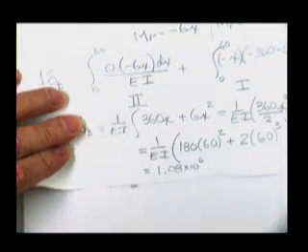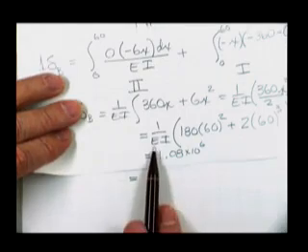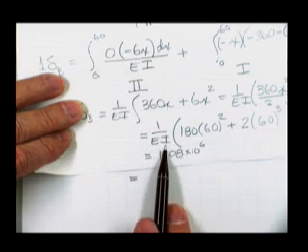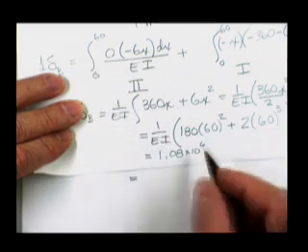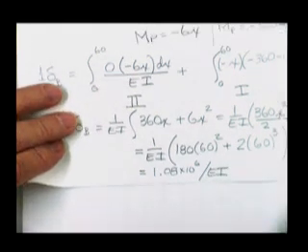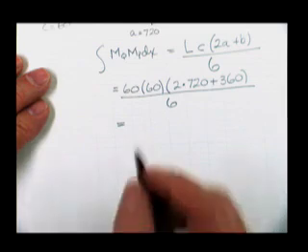Sure sounds like a lot of deflection. Not necessarily a problem because we're going to divide by 30 times 10 to the 3rd, ksi, and the moment of inertia, whatever it is. So that divided by EI. And you guys usually pick up my mistakes, so this ought to turn out to be the same. It does? That's nice.